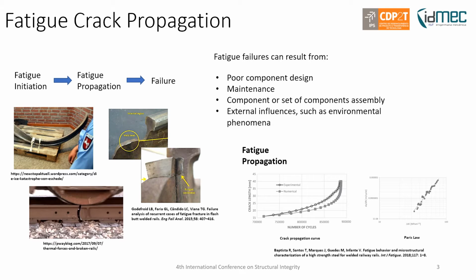In the case of fatigue crack propagation, what we need to know is the crack length along a given number of cycles. And taking this crack propagation curve, we can of course derive the Paris law or any material behavior equivalent equation that allows for the control and fatigue life prediction of the crack.